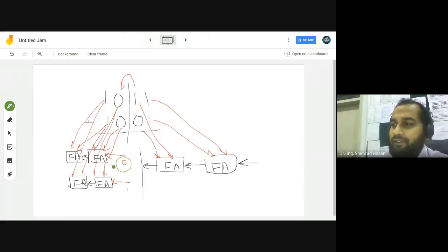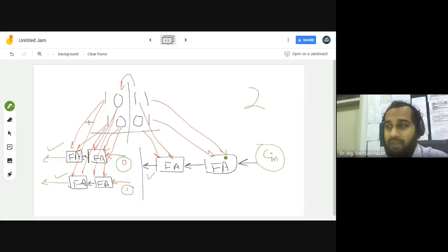So this same thing is working like this. It has got this carry input and it has also got this carry input. So all of them, these two and these two, are going to work at the same time. And these two and these two are also going to work at the same time, because all of their inputs are now decided. So by the time you get this result, you also get this result and this result. Is this clear? So you're going to take just 2 steps to get any of these results. Yes, I got it.